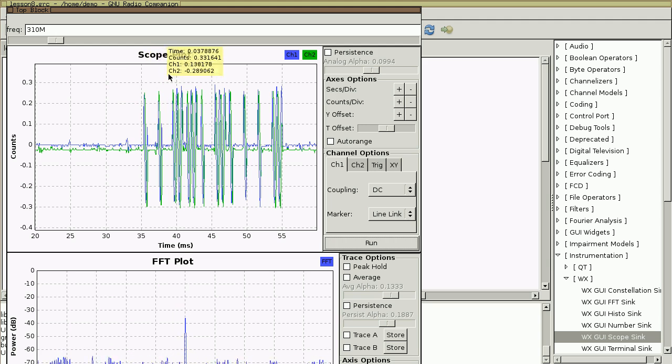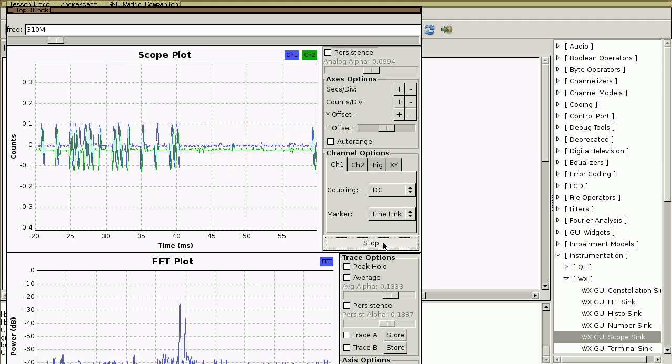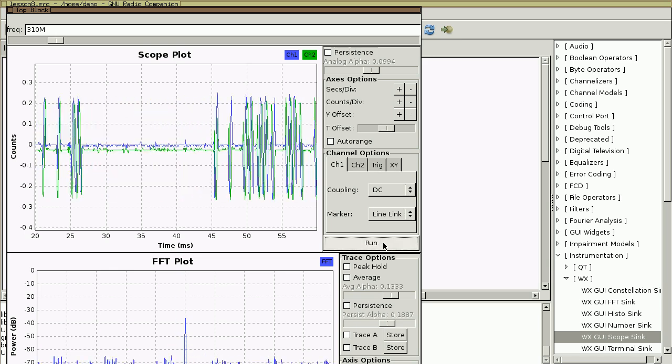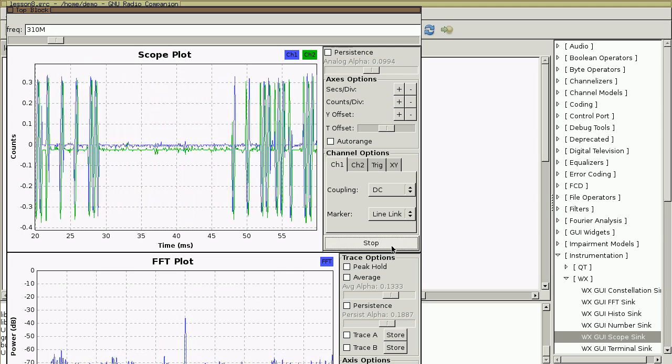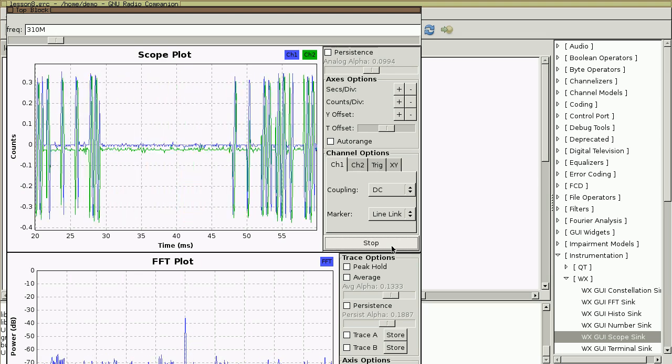And sometimes you might see the end of a pulse lining up, or in this case we see the beginning of a pulse lining up. And if I release the button and press it again, and run this some more and stop it and try to get that whole set of pulses on screen at once, we see the same exact pattern. Short, short, long, long, short, long, short, short, short, long. The same pattern of 10 bits over and over and over again in these groups of 10 pulses.